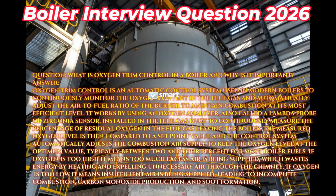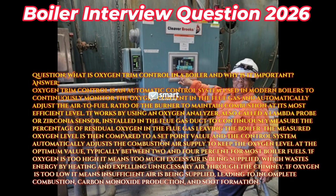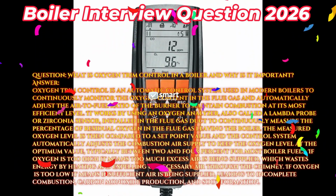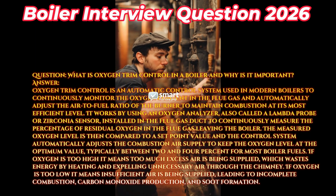Question. What is oxygen trim control in a boiler and why is it important? Answer. Oxygen trim control is an automatic control system used in modern boilers to continuously monitor the oxygen content in the flue gas and automatically adjust the air-to-fuel ratio of the burner to maintain combustion at its most efficient level. It works by using an oxygen analyzer, also called a lambda probe or zirconia sensor, installed in the flue gas duct to continuously measure the percentage of residual oxygen in the flue gas leaving the boiler.